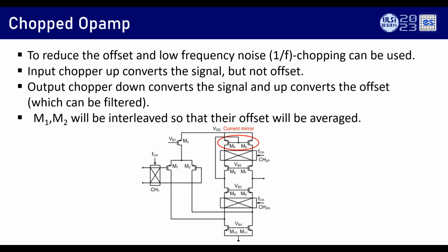The operational amplifier is only one stage. There's only one stage, that's it. Because you have an operational amplifier followed by that PMOS current source in the bandgap core, already it is two stages. Now, if you make the operational amplifier with two stages, then it becomes a pain for compensating. No, the first stage is the one you need to chop. The second stage you don't care. So you do the first stage chopping, the second stage you don't care.